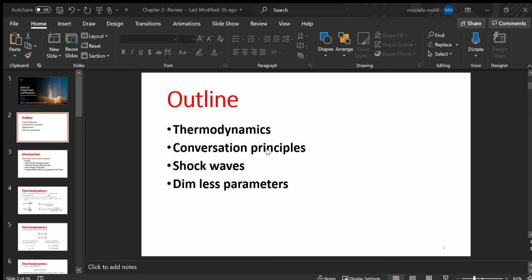That one is usually negligible, but there are some people who claim that the degree of freedom of diatomic gases is more, but it depends. For air, we just stop at 5 essentially, right? So you're going to get 7/5 here, which is going to give you roughly 1.4.